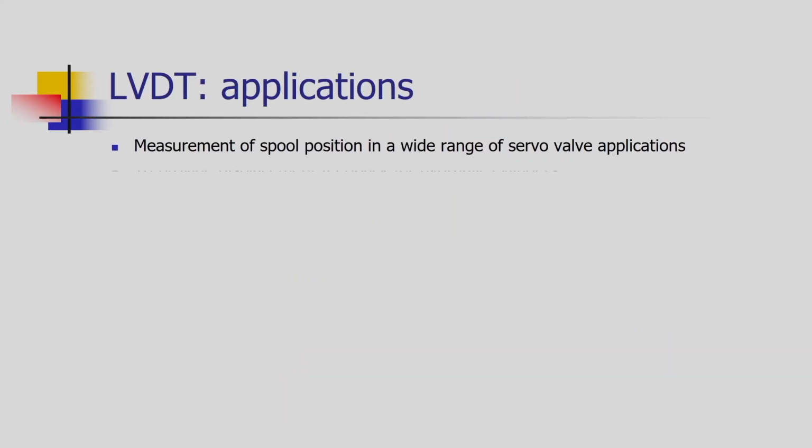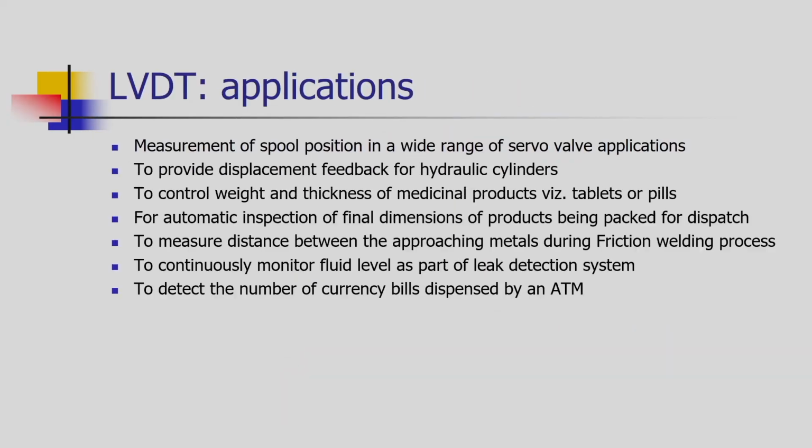A few more applications are there in front of you. Some of the applications I have already talked about, that is, spool position measurement or control of spool position. Then displacement feedback in hydraulic cylinders, because hydraulic cylinders are operated by high pressurized fluid. Based on the viscosity of the fluid, there may be chances of over travel. To control the over travel, we are using LVDT sensors.